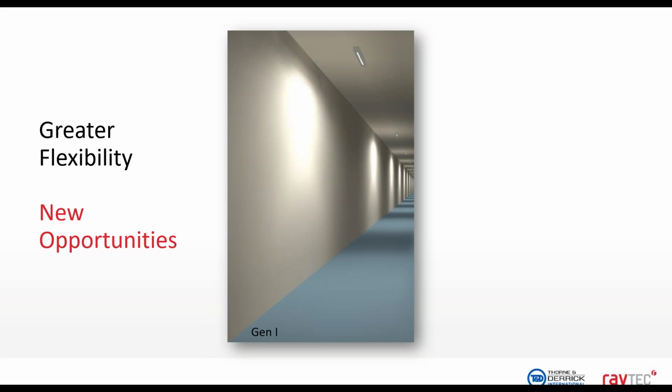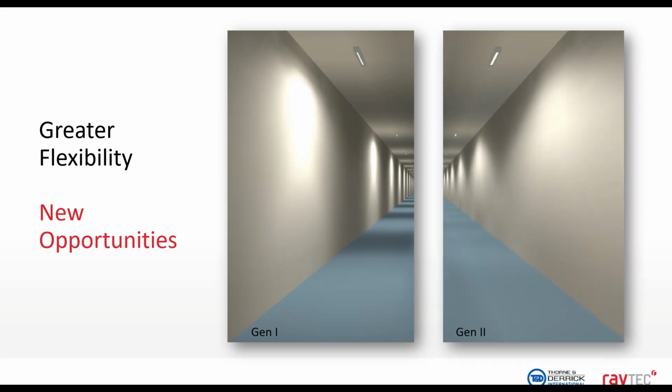It's where we want to put the light is along the ground to get a nice even illumination along the corridor. If you compare that same design but using the new Linear Gen 2, and this is utilizing an optic which is specifically designed for corridors, we can see that the floors are much more even light distribution. So less of that light's being wasted against the wall. There's less of a bright white spot against the wall there, and much more uniform illumination along the ground, free from dark areas. So again, we think that's a big improvement, not just on the increase in power, but also the flexibility which these new optics provide.